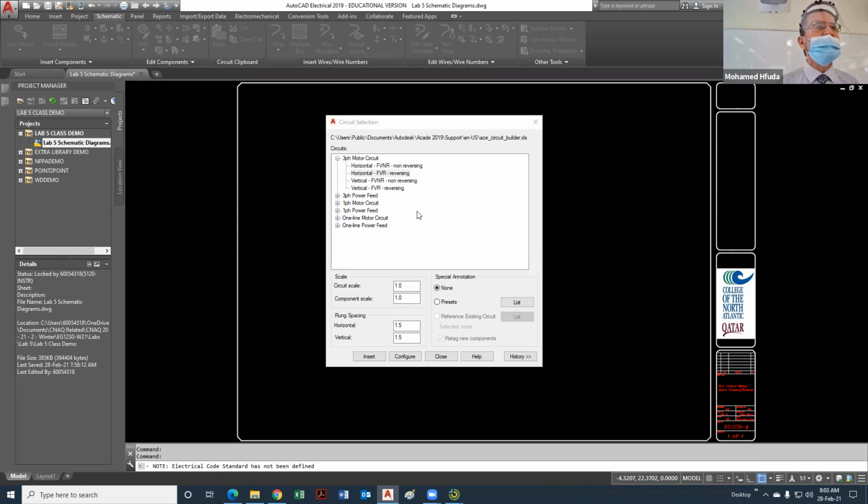Why is the star delta reduced voltage starting? We start with the windings configured as star, or a Y configuration. That means each winding of the three will see the line-to-ground voltage, which is the line-to-line voltage divided by √3.